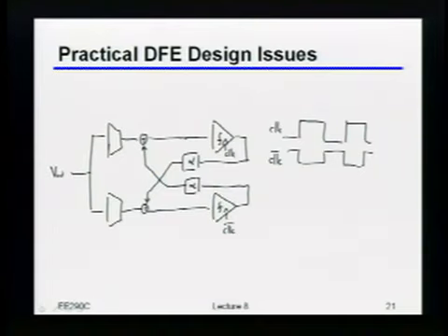Okay, so the reason I was mentioning this was, again, I may have gone to this interleaving because, as an example, I wanted to relax some of the constraints on my comparator. But notice, because I'm actually closing this first tap here, I still have the timing constraint of making the decision, going through this scaling, feeding back onto this analog node, and having it settle all before that next bit time, right?